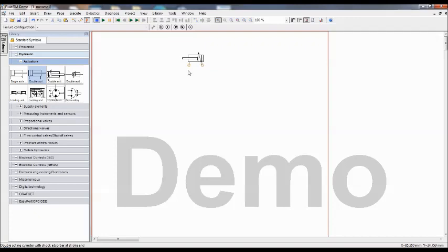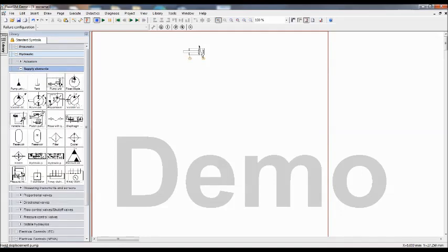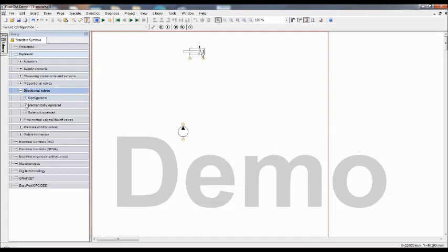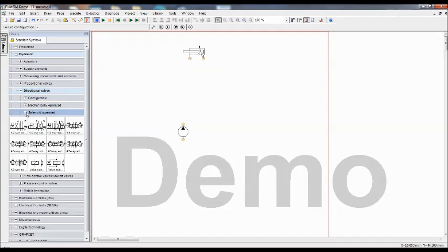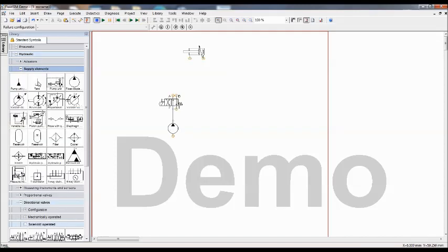Now, in the supply elements, sorry, not this one. Let me take first the 4x2 direction control valve, solenoid operated. The first valve is as per the requirement, and the pump, and go to the supply elements, tank. One more tank is required. Since it is a fixed displacement pump, protection is required against overpressure, so we have to use a pressure relief valve.